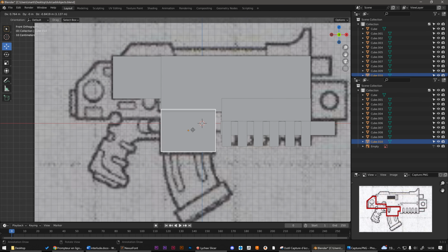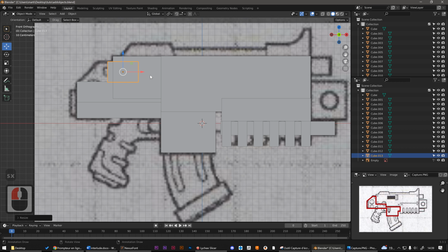And then to do the bevel, since we don't yet know how to create oblique objects, well, we're going to duplicate this one, move it along the axis, and with a scale along the x-axis, we will make sure that these two edges have the same length. So let's make it a little bigger like that, and there we can rotate the object by -45 degrees. Since the view is aligned on the axis we want to rotate on, I just need to press R and hit -45 degrees on my keyboard.